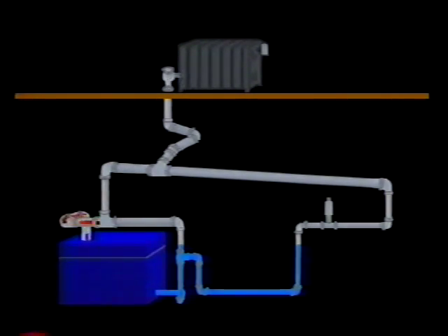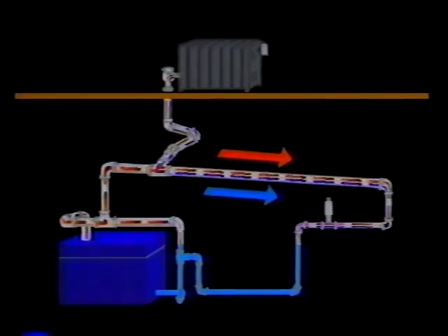The steam travels from the header through the system main to the radiators, which are connected off of the main. In this example, the main also carries the condensate back to the return. Notice that the condensate flows in the same direction as the steam in the main.